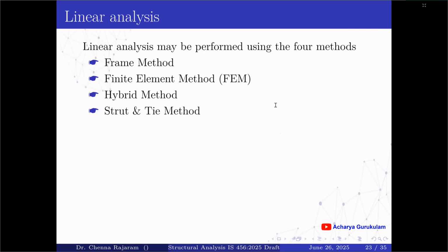The finite element method shall be used when structures consist of members such as structural walls and slabs. The appropriateness of the results from this analysis shall be ensured before considering them in design. Stress concentrations at points of application of concentrated loads, and at reentrant angles or corners and openings in slabs, shall be addressed in the design stage.